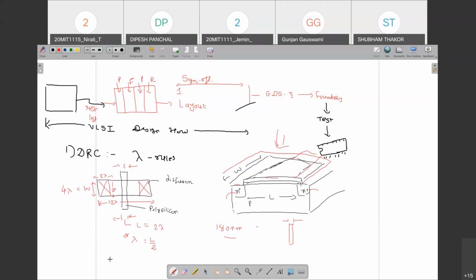We have an n-well, and we have to place the n-well; for that we have rules. We have to place the vias between two metals, and it has to pass with some lambda rule. So these are the lambda DRC checks. If there is a DRC error, you definitely have to modify your layout. So the first checkpoint is DRC, design rule check.